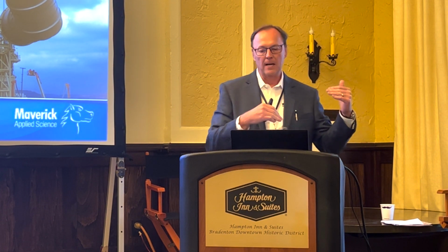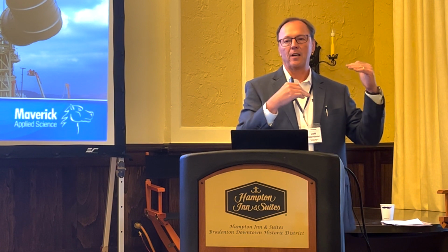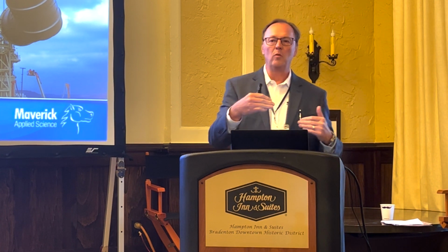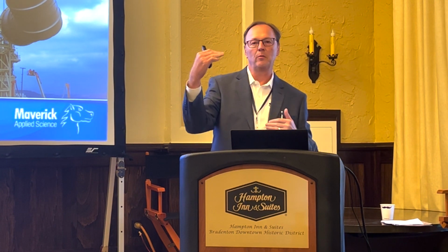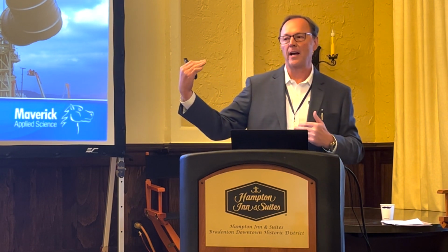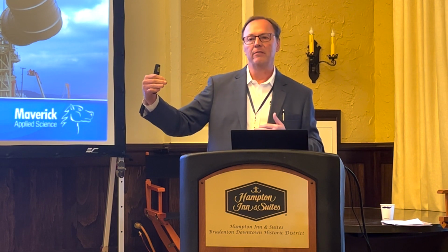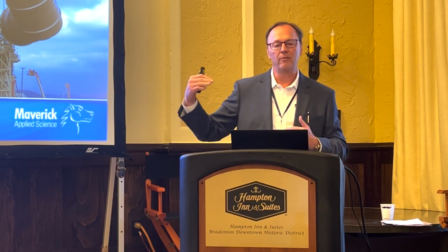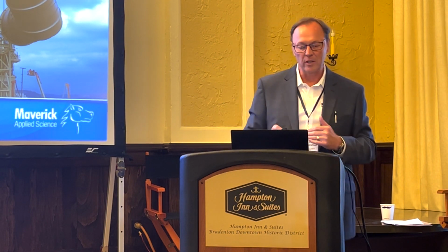We want to say, provide an inspection and test plan. And we want to witness material testing. We want to witness fabrication points. We want to say hold points at completion of the corrosion barrier, hold points at installation of nozzles and assembly of components, and maybe final testing or something like that. You want to be very specific, exactly what you want.